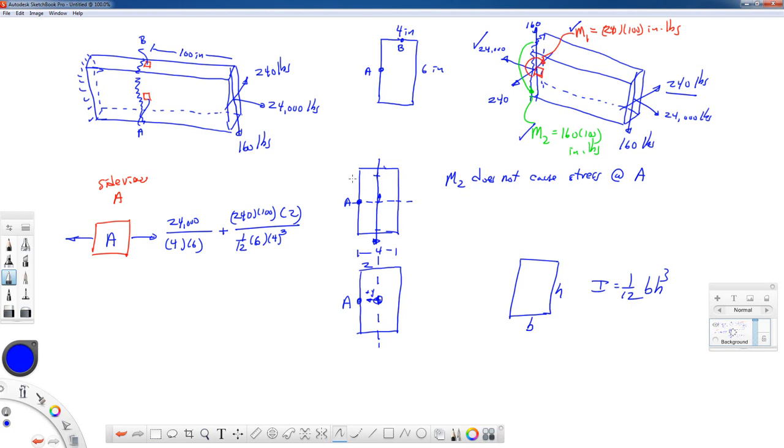The shear force will always point to what it thinks is the top of the cross-section. And you can go from the point to the top or the point to the bottom of the cross-section, doesn't matter. So for the 160-pound force, what I would shade in would be the top half of this cross-section. Notice how the shear force goes down on this far side, on the right side. That's going to cause a shearing stress that goes down this way at point A. Even if we just have one of those shearing stress arrows figured out, we can pencil in the rest of them for equilibrium.